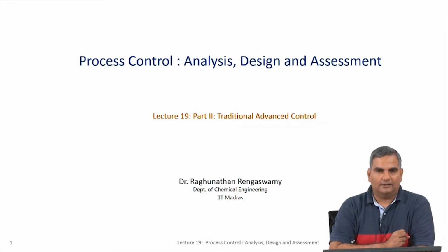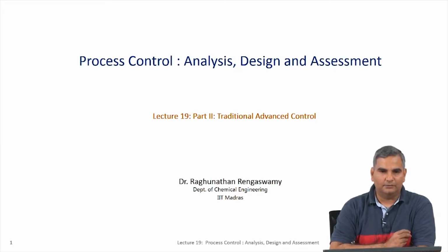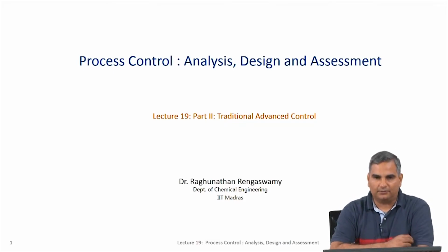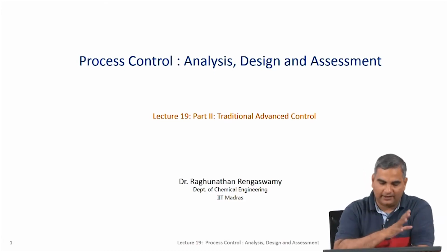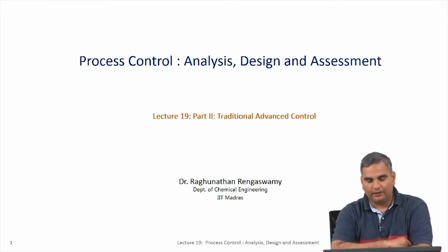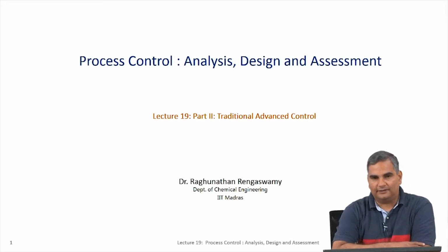So, the ideas of inverse response, unstable control, and time delay systems are easily understood when we think about controller tuning using a direct synthesis approach, because that will allow you to understand what are the issues that come about if you have these types of process behavior, and what are the fixes which will become readily apparent when you look at this direct synthesis kind of tuning.